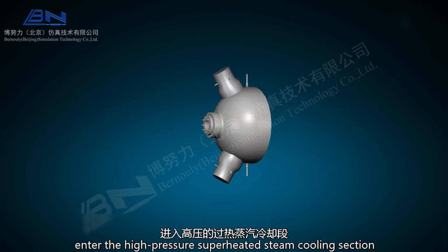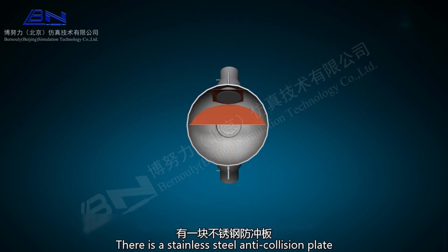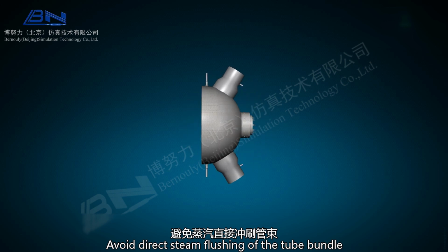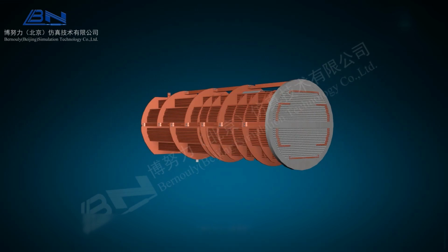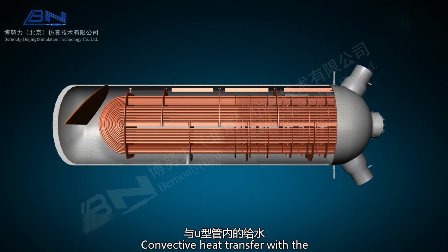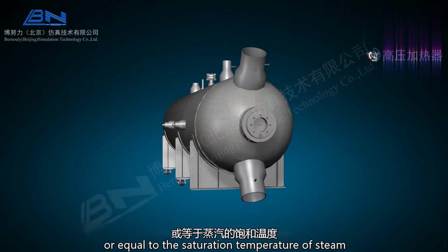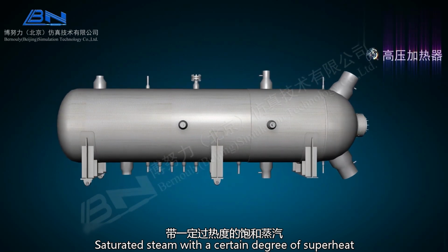The high-pressure superheated steam extracted from the steam turbine first enters the superheated steam cooling section. Below the steam inlet connection, there is a stainless steel anti-collision plate to avoid direct steam flushing of the tube bundle. The steam is separated by several partitions along the edge, forming an S-shaped flow through the staggered spacing arrangement, with convective heat transfer with the feed water inside the U-shaped tube, so the water is heated to a temperature higher than or equal to the saturation temperature of the steam, leaving saturated steam with a certain degree of superheat.